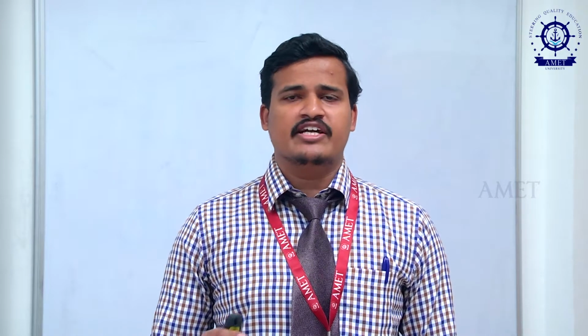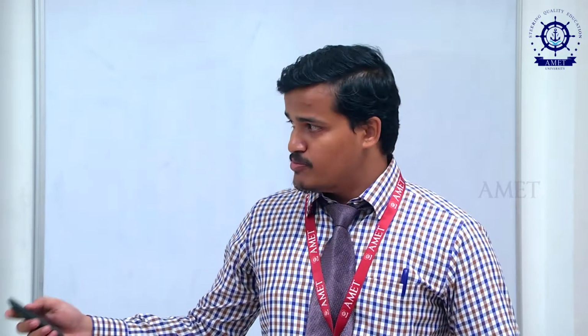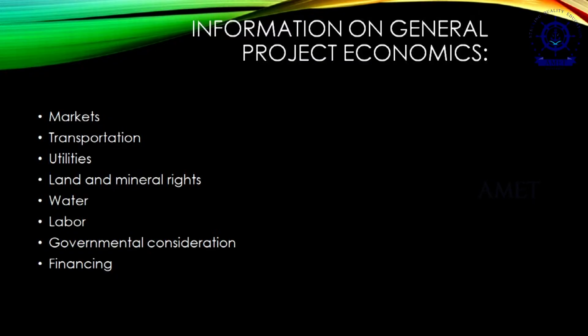In order to get clear information about the ore deposit, they will definitely go for diamond drilling, because they have to follow the JORC code. JORC is the Joint Ore Reserves Committee's guidelines that show how the diamond drilling patterns have to be, and the exact pattern will be given by the JORC code. Exploration data will be collected according to that, and only then will the feasibility report be prepared and submitted for further financial aid.